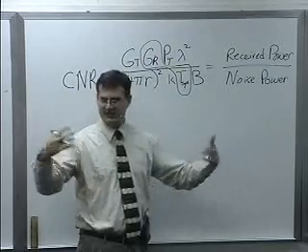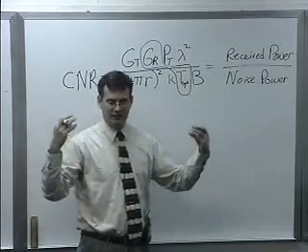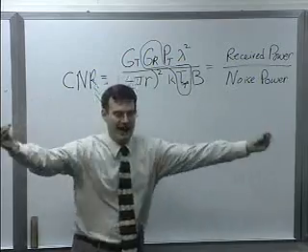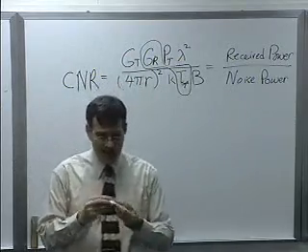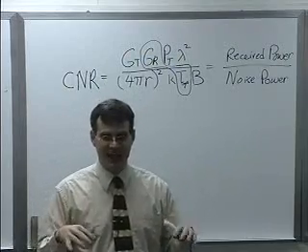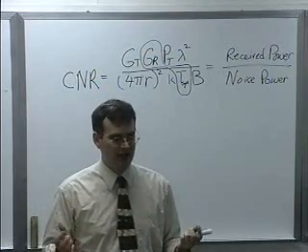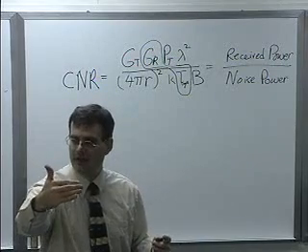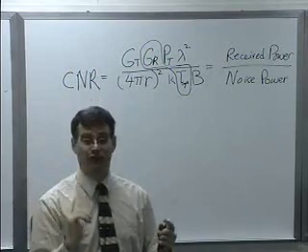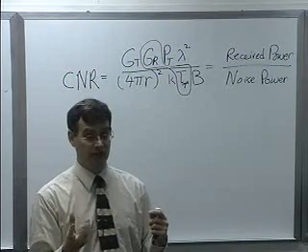If you're using an established protocol and an established application where you're going to have this much distance between you, then a lot of times, especially on Earth stations, they ask how good is the Earth station? They'll say, what's your G over T? What's your linear gain of your receiver antenna over the physical temperature of your receiver?